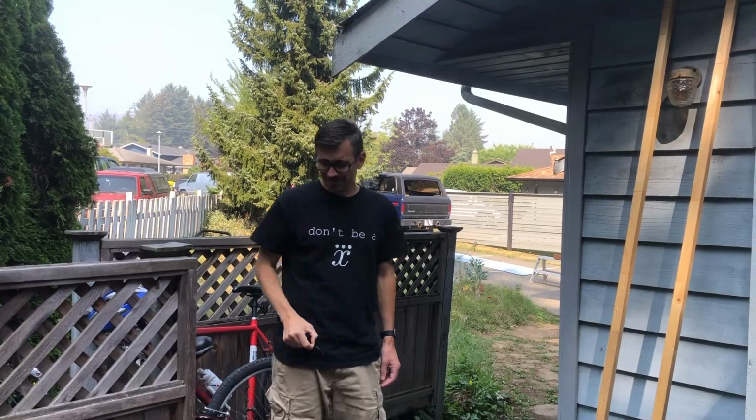But what happens if we violate this wattage rule? This is an experimental physics course, so let's do an experiment. What we have here is a 1/8 of a watt 10 ohm resistor. Now 1/8 of a watt means that V squared over R is such that we can only put about a volt through this thing before exceeding its power. Let's see what happens if we try to put a lot more on there.